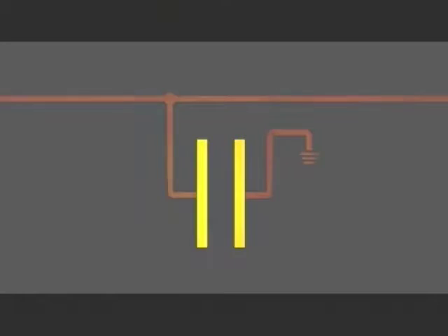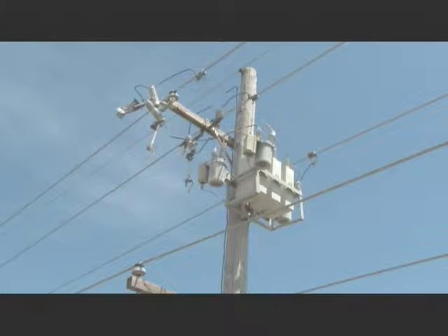If the capacitor is connected to an AC circuit, the capacitor is constantly charging and discharging due to the cycling effect of alternating current. This charging and discharging causes current to flow into and out of the capacitor. When capacitors are added to a distribution feeder, the resulting current flow can be used to increase the efficiency of the feeder by changing the power factor.